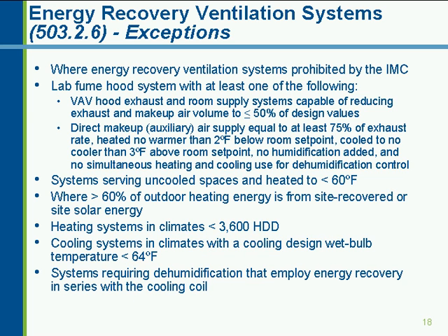There are a number of exceptions to the ERV, or energy recovery ventilator requirement. If energy recovery is prohibited for that application by the IMC, the International Mechanical Code, you're not required to do it. Examples of that would be spaces that are exhausting toxic fumes or kitchen grease hoods. If you have those types of applications, you're not required to do energy recovery from them. If you've got a laboratory fume hood system,